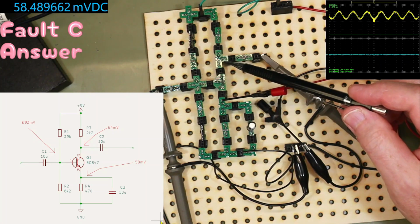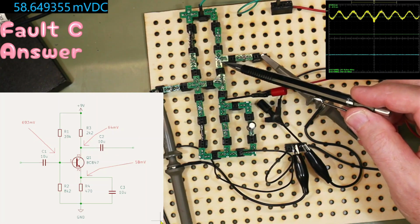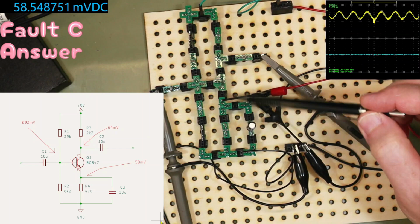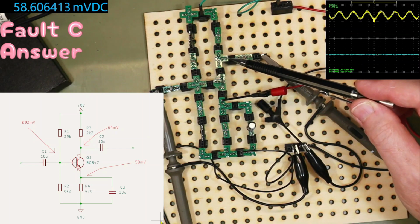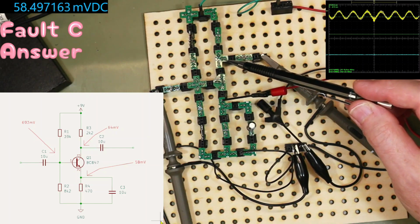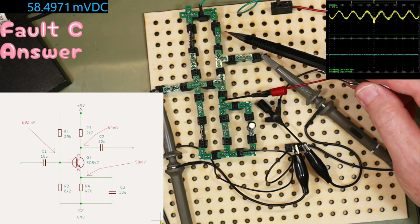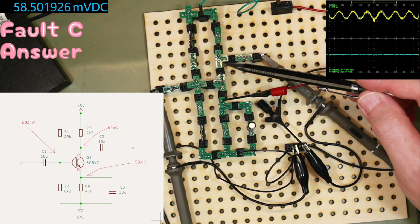At this point here, which is the collector, again 64 millivolts. You know, there's no current. Why is there no current? Well, there's no current because there must be a problem with R3, because we know that if R3 was correct, that would be around 5 volts.